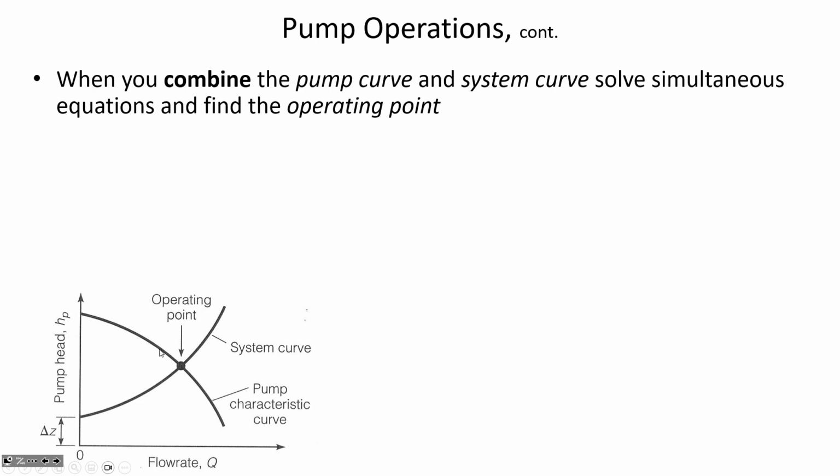We have the typical shape of the pump curve, which is downward as you move to the right. The increasing system curve just says that as the flow rate increases, the head losses are going to be going up. That's why the curve is increasing for a system curve: with each increase in flow rate, there's more and more friction losses.